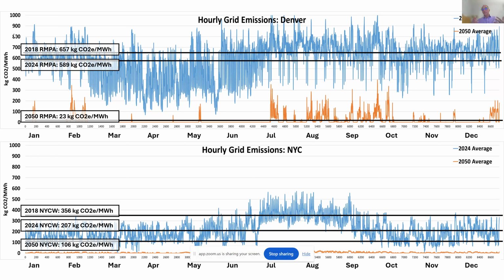Those black lines that I've put on this are the annualized values. So again, I mentioned that I was picking on ASHRAE Standard 228 for its eGRID 2018 values. That is the single value running across the top that you would be using if doing net zero carbon using that standard. You would be analyzing your building with this single value over the entire year versus this much messier blue line, or this future orange projection, or anything between. And these are the importances of using an hourly analysis over something annualized.